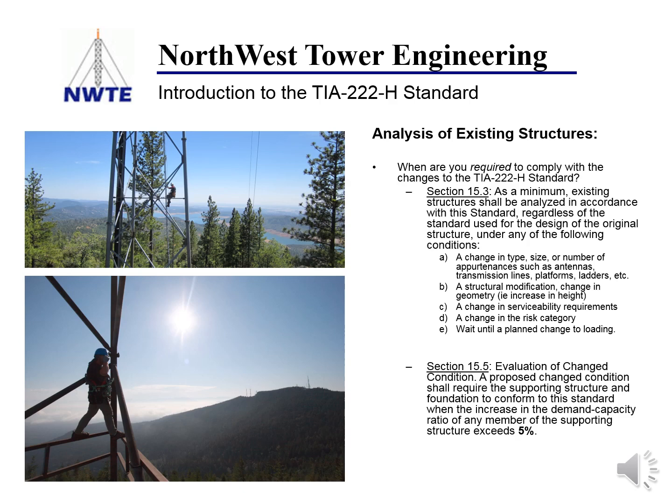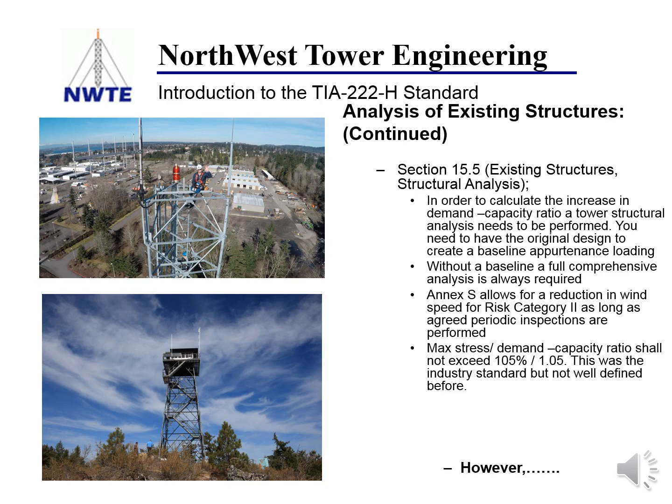Now this was added, section 15.5, and it talks about when the increase in demand capacity ratio of any member of the structure exceeds 5%, you are required to run the analysis. So here we go, section 15.5.